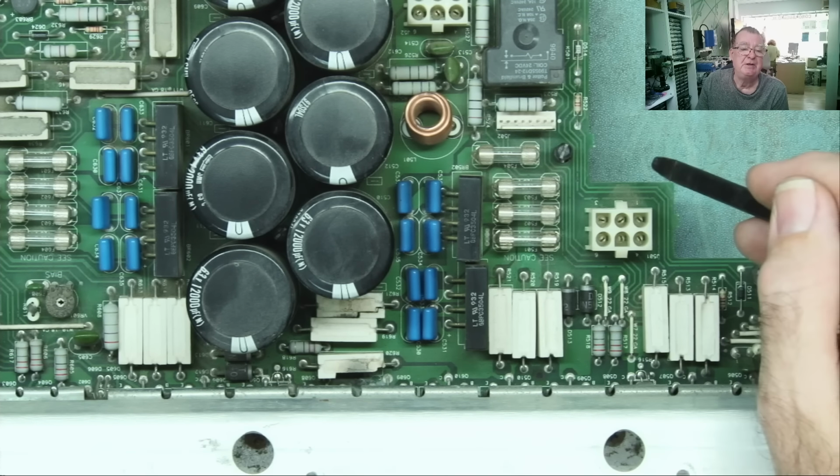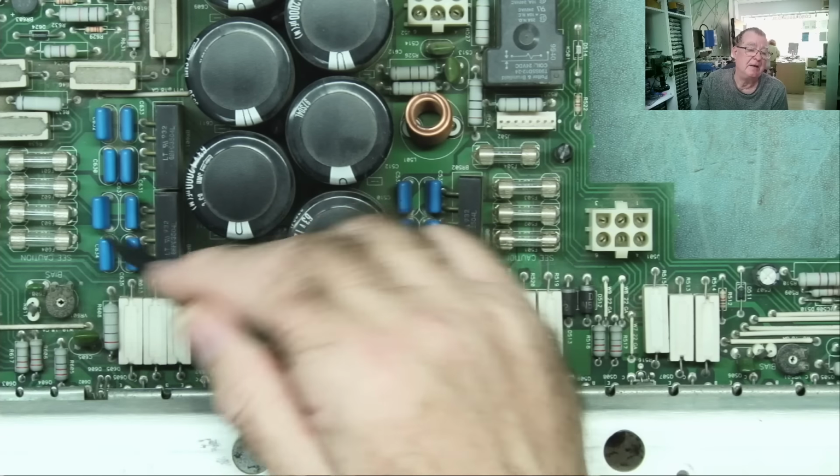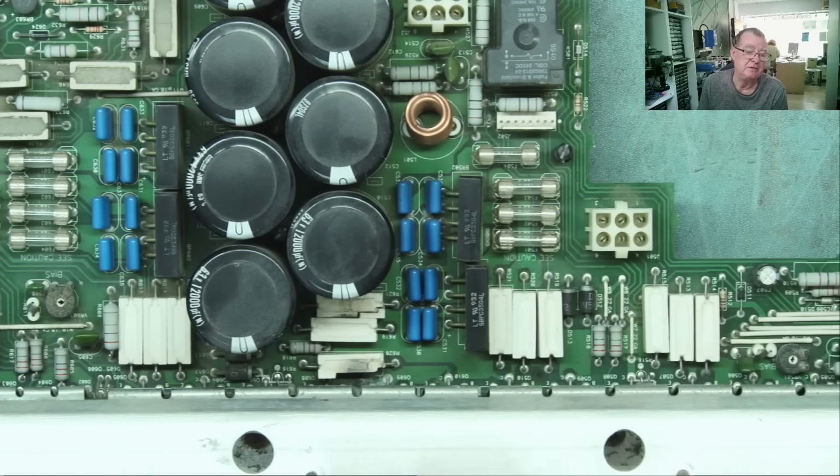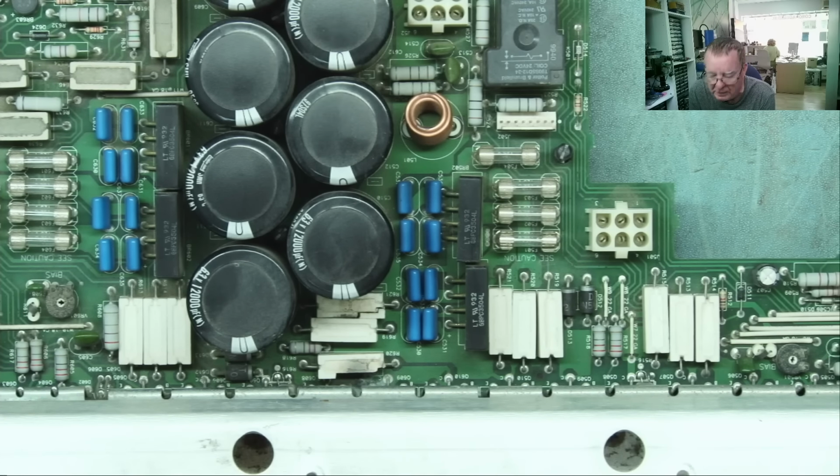So basically anything in the current path from the mains coming in via the rectifiers to the devices could have failed as well. Number 2, fuses. Fuses are a protection device. They are designed to fail in a fault condition. So fuses should be, again, one of the first things you test.